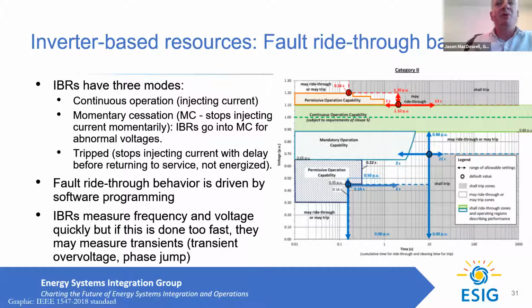So Nick is going to talk more about the transient stability considerations, about what happens after we initially ride through an electrical disturbance and how the system recovers. But today, as long as the system conditions are known, how weak is the interconnection, what capabilities do we need to deploy with the inverter-based resources, what settings do we need to deploy for inverter-based resources in every application, it's not an issue to ride through the capabilities that we need to support the grid stability today.